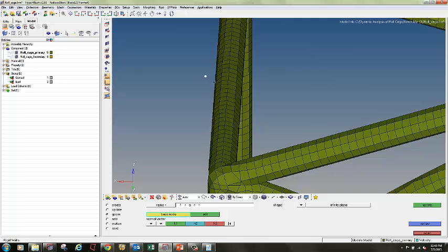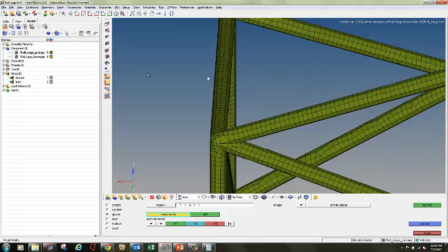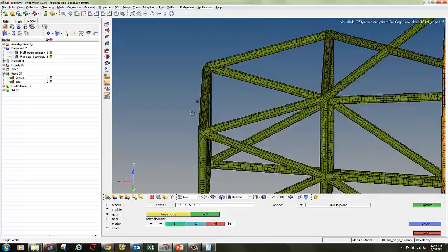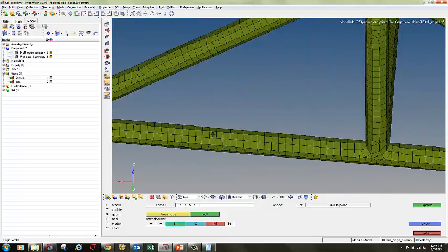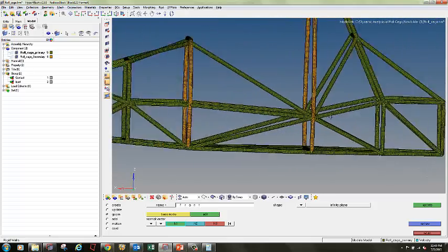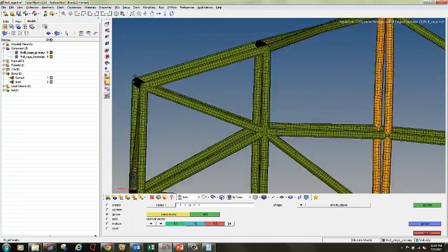You can create a rigid wall at whatever distance you want away from the roll cage, and select the normal vector. The normal vector has to be in the opposite direction of the roll cage's velocity. If I pick X, it will take the positive X axis, which is in the same direction, so the impact will not happen. So I have to select N1, N2 and define the direction. I will pick any straight line for N1, N2. I can even pick this also.